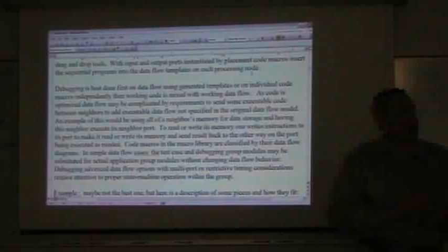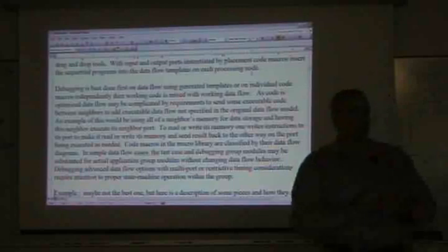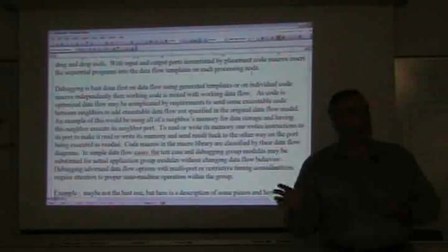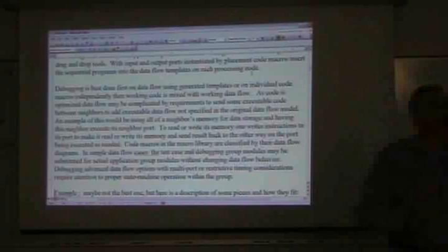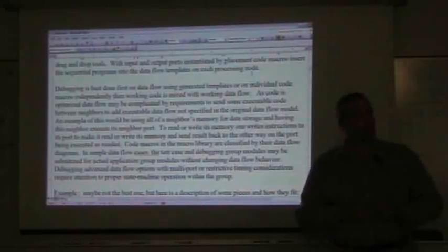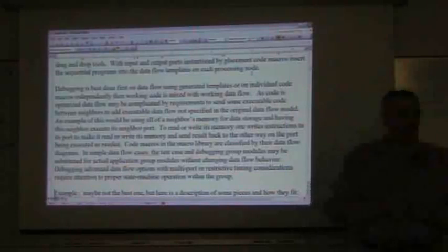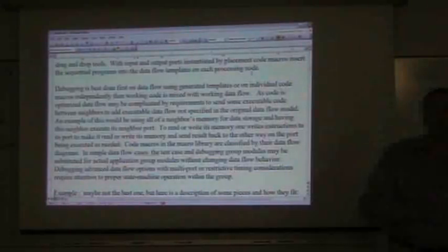Now, to linearize it, I said, okay, a simple way to do that would be to have a data table with 64 values in it and read 2 of them and interpolate between them. So I just took a neighbor and put a table on it. Now that neighbor has no code. What it's doing is, after it's loaded its table into RAM, it jumps to the port adjacent to the node with the A to D. So it's trying to execute the port connected to the node that's doing the digitizing.